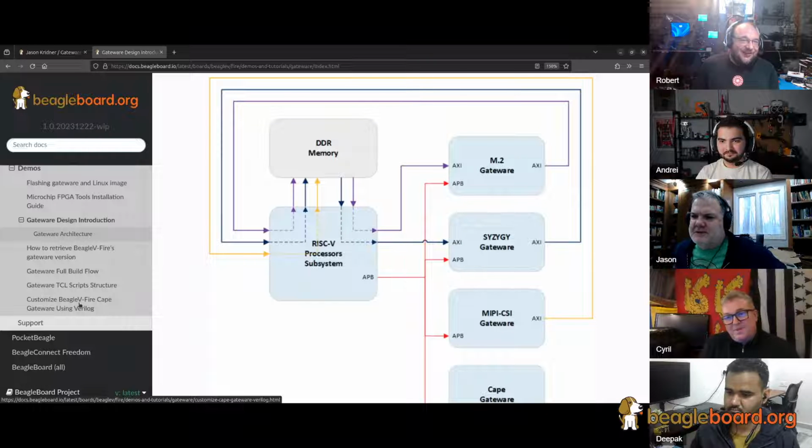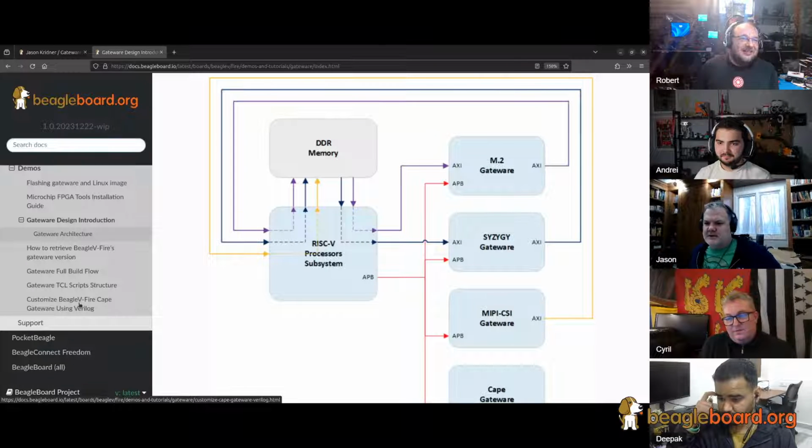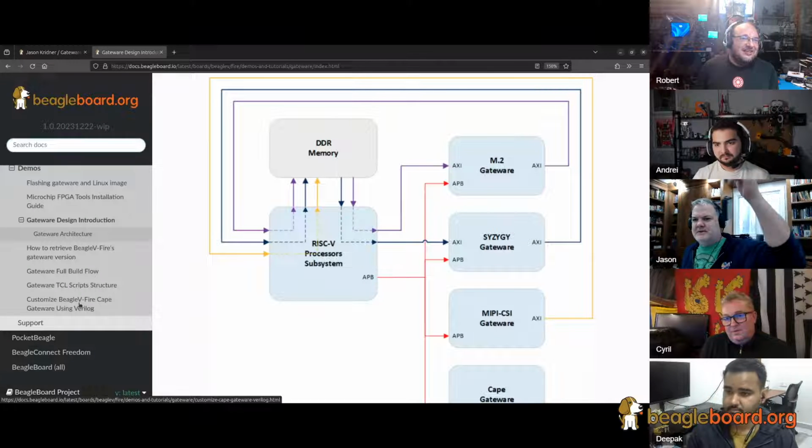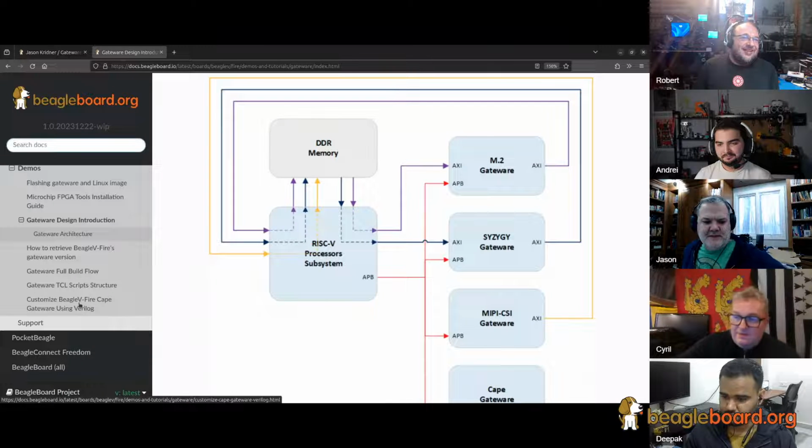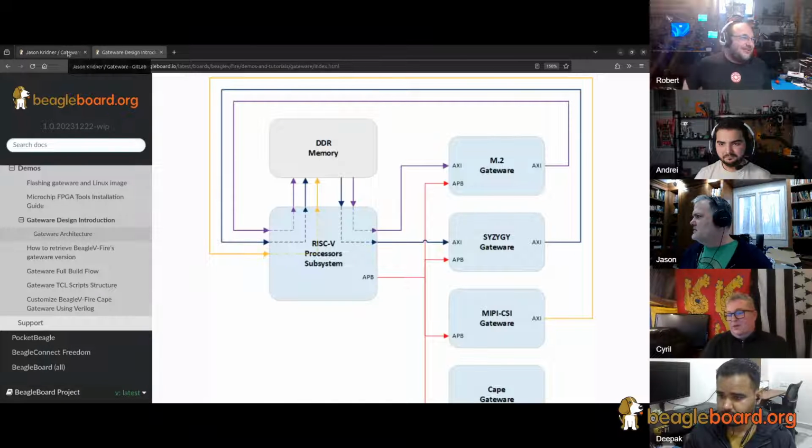To be fair, you can fix that from a serial cable in the U-Boot prompt. With just a serial cable, you don't need to redo the flash on the SPI, because you can change what the overlays are at the U-Boot command line. So that one requires a serial loader. Only when you've done really nasty things do you need to get something like the FlashPro 5 and the Tag-Connect. And even then you don't need the FlashPro 5 if you use the BeagleBone Black with a direct C cable.